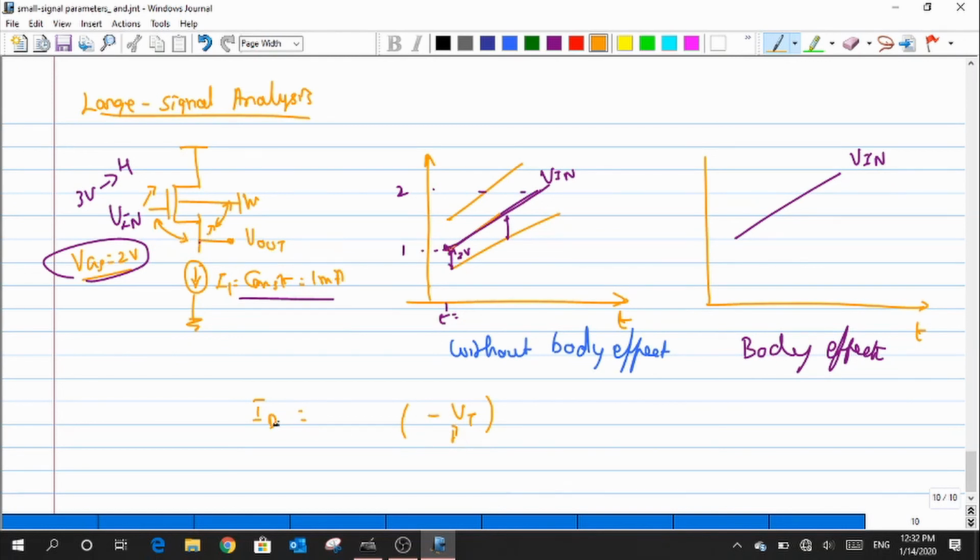That also increases. So due to which the current increases or reduces? Because it is VGS minus VT, right? Because of this quantity getting reduced, the current value is getting reduced. So how will I keep this current the same? I don't want this quantity to get reduced, which means that the value of VGS is supposed to rise up. How will I make this VGS larger? I have to make a larger gap between the source and the gate. So you will get a graph something like this, a kind of curvature. Okay, is that clear, making sense for your Vout?